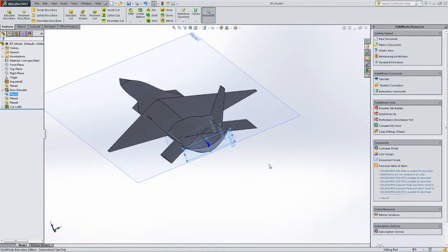It's a 3/4 inch force balance, and the mount in the model is a 0.839 inch diameter carbon fiber tube with a 0.754 inside diameter, so there's 4 thousandths of clearance on this force balance, which is perfect.